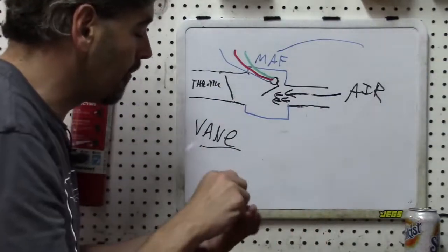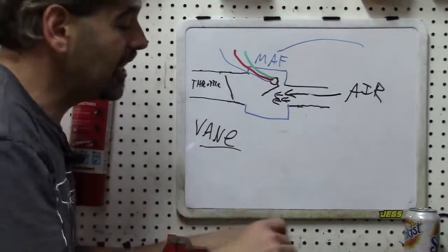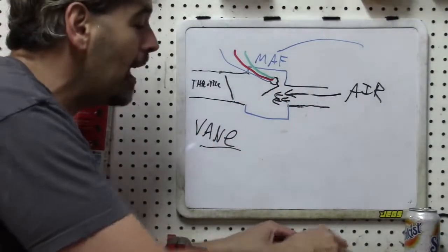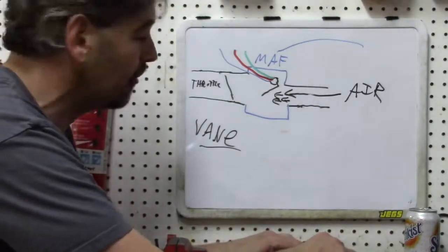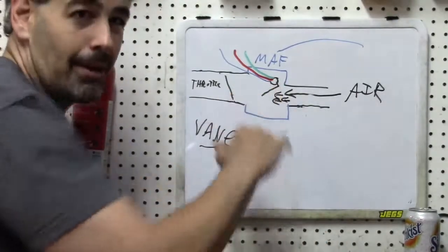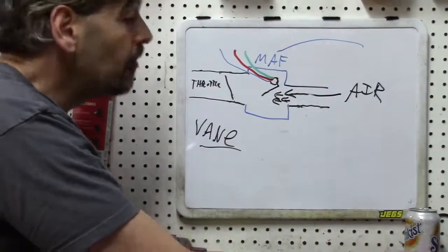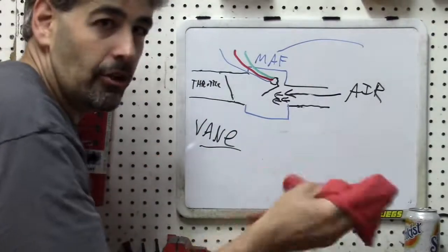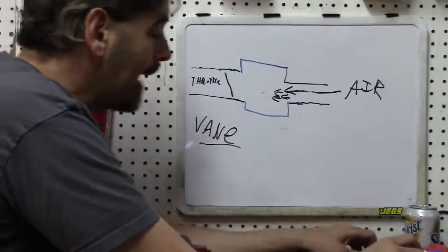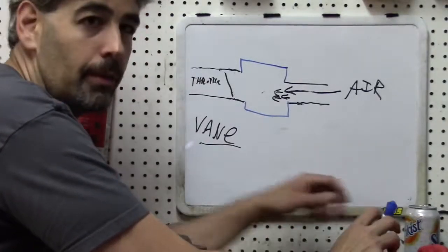Terrible system. One of the most common things that would happen is this hinge would get gummed up. You've seen the inside of a throttle body, I'm sure. If you are watching this channel as an advanced do-it-yourselfer, you've certainly done stuff with a throttle body. Very bad design, obviously, because of carbon buildup. Very inaccurate. So it is no longer used, and now they use electronic versions. So I'm familiar with, I can think of 3 other versions, and there certainly may be more.